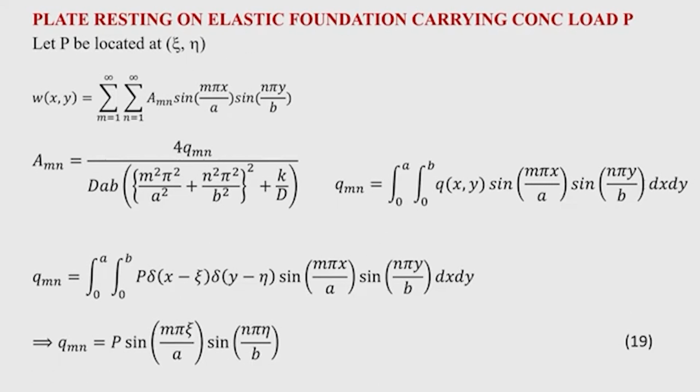So, let us see another case where the rectangular plate is resting on an elastic foundation, but instead of a uniformly distributed load it carries a concentrated load. A concentrated load is a discrete quantity and therefore the loading function becomes discontinuous. Because of the discontinuity, the loading function is not differentiable. So, that is the problem.